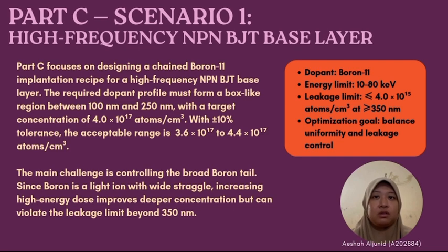The most critical constraint is the leakage boundary. At 350 nanometers and deeper, the boron concentration must not exceed 4 times 10 to the power of 15 atoms per cubic centimeter. Therefore, the optimization challenge is to form a box-like profile while preventing the boron tail from extending too deeply into the silicon substrate.